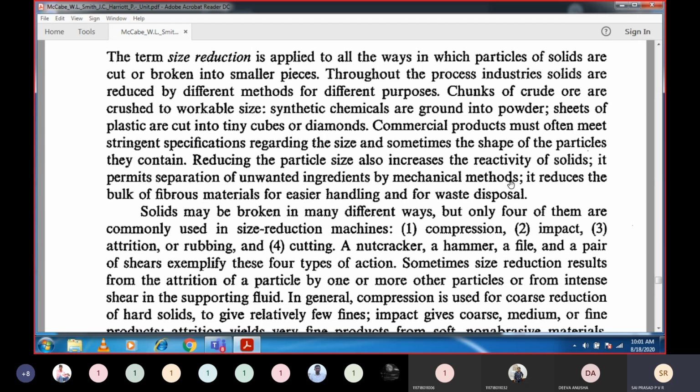Similarly, take the case of separation of ferrous and non-ferrous materials, magnetic and non-magnetic materials. Crush them properly, and then as the powders fall onto the bed, you keep a magnet at the driven pulley. Then what will happen? All the magnetic materials will be attracted to it.